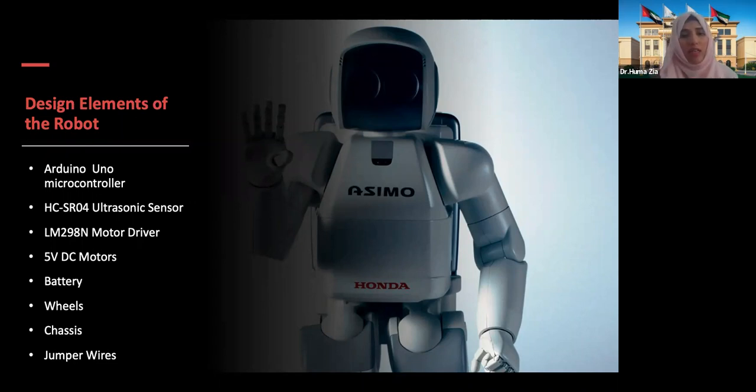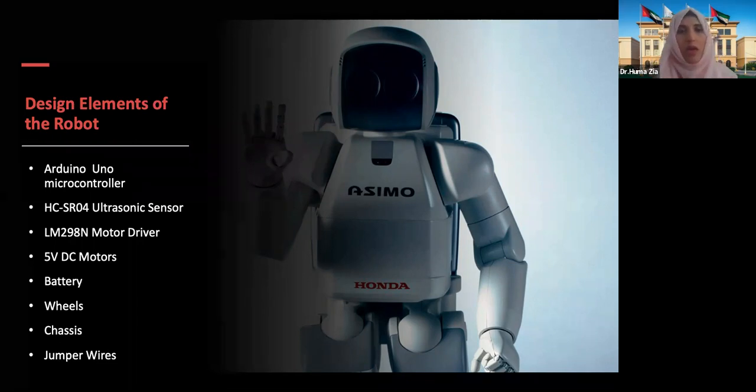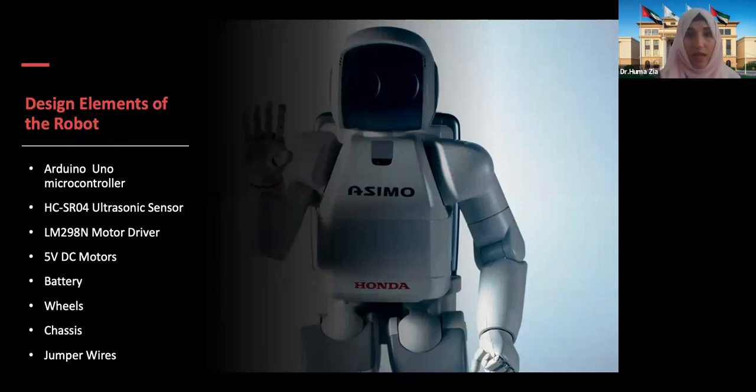What happens is that it cannot detect from the side if there is some obstacle on the right side or on the left side. It can detect obstacles in the front. If you want very precise, accurate obstacle avoidance in a robot, then you're going to maybe use multiple ultrasonic sensors, or you could incorporate some other type of distance measuring or detection sensor as well, like an IR sensor.